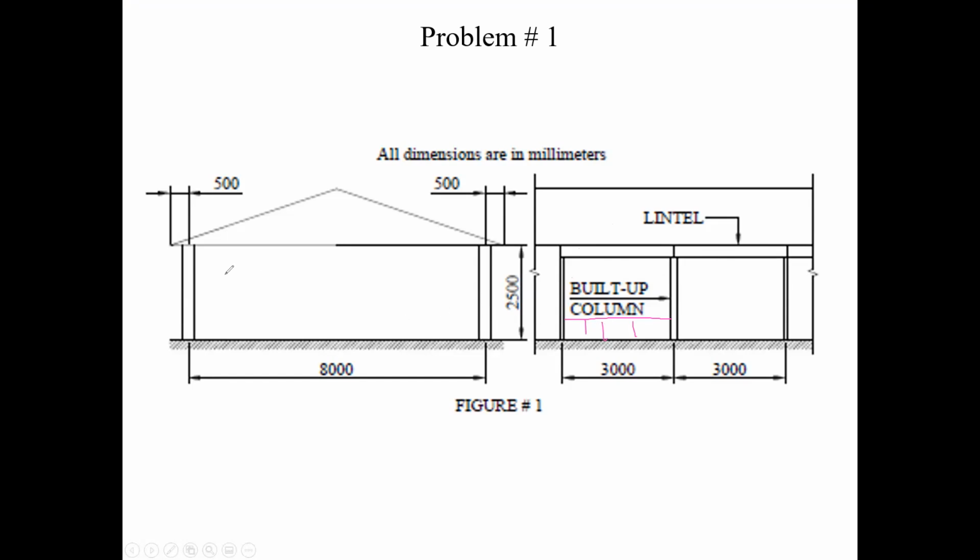So here, I'm looking at a cross section or an elevation of the house. The trusses are spanning 8 meters. And you just have to remember that in theory, half the load goes there, half the load goes there, and therefore from here to here becomes a tributary width that is brought to this supporting member here, and therefore you'll be able to calculate the loads that are being transmitted along the wall here. So that's what you should be starting to visualize a bit in your head.